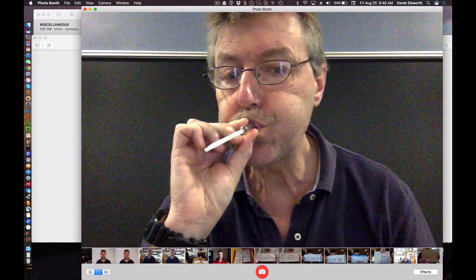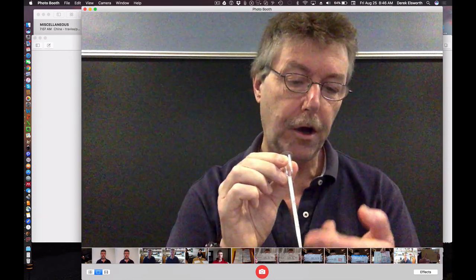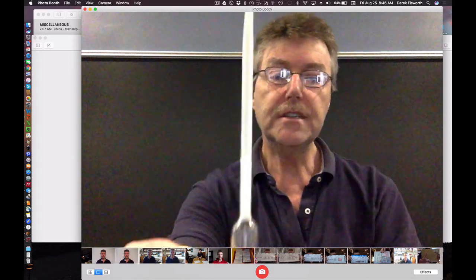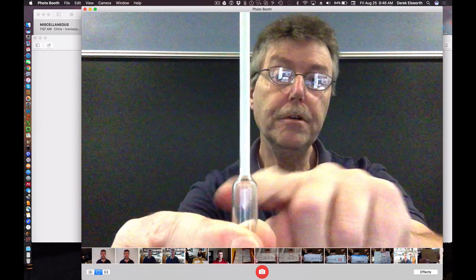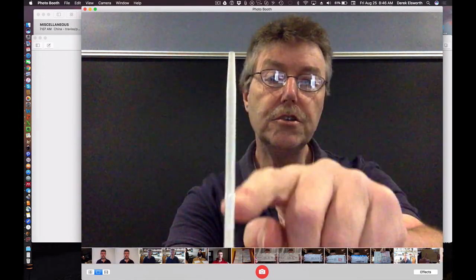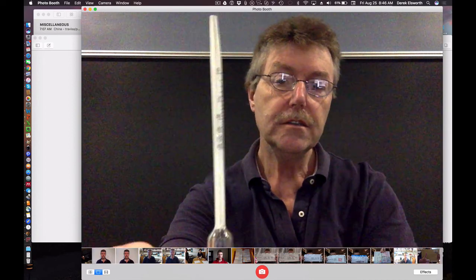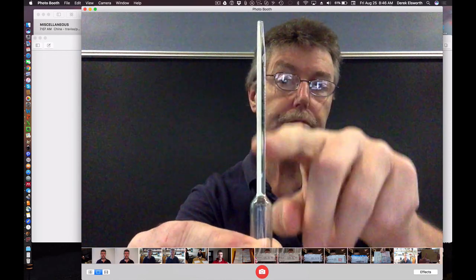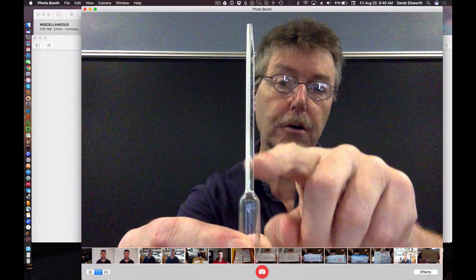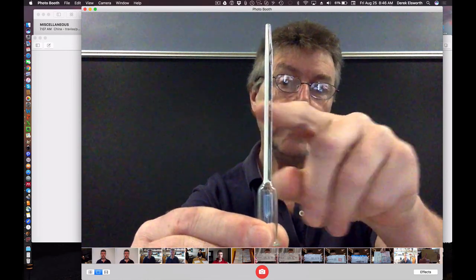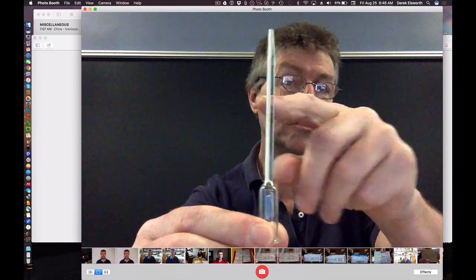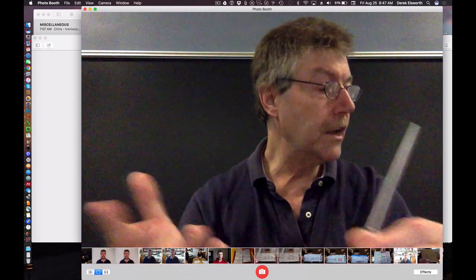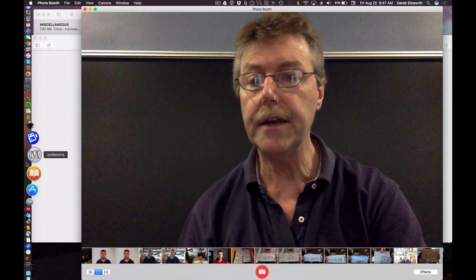You blow until water comes out of the bottom, so you fill up this capillary tube, and then you stand it upside down. Now this is open, and you can look within this tube. It's graduated on the side to give you the alcohol content, which is the height to which this will stand up within this tube. It's really controlled by the surface tension across the top of this tube, open at the bottom here, which is at atmospheric pressure. And so it's a direct analog to the system that we'll look at right now.